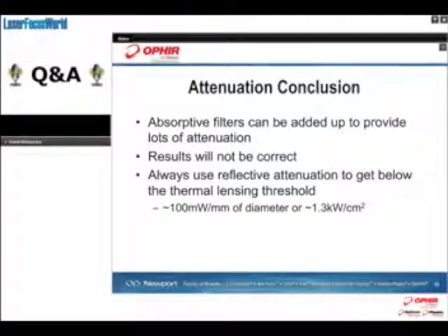Okay. As far as the measurement at focus, one question wants to know how do you know the sensor is level? And I think what that means is when you're doing a through focus measurement, how do you know your sensor is moving parallel with the beam? Well, that again is a question of fixturing, and any time you're trying to do precise measurements, you do have to pay attention to how you've set up your profiler.